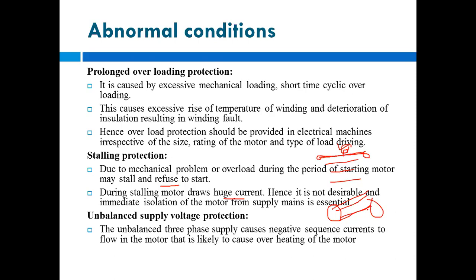Okay, and if there is also overload at the starting of the motor, so your motor is refusing to start. If it refuses to start, what happens? You are giving supply but your motor is not starting, so it will draw a huge current. Okay, the motor will draw a huge current.